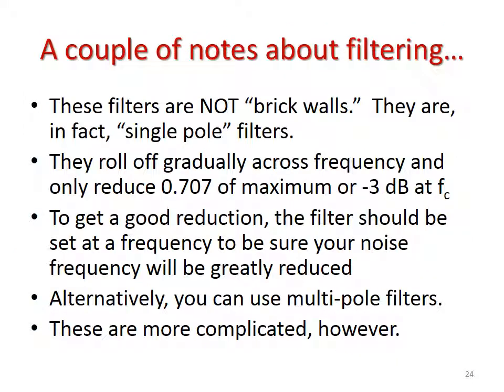So a couple other notes about filtering. These filters are not brick walls. They are single pole filters. What that means is that it doesn't immediately stop at that selected cutoff frequency. You're not immediately shutting everything off for a low pass filter anything above that 0.707 point. It allows some of it through, and even at the lower frequencies, you still have some smoothing of those curves. So they're not perfect filters.